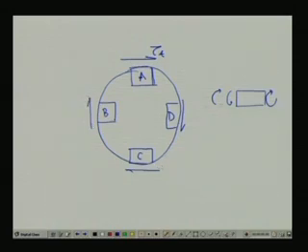And if we look at the vertical shear stresses, what is happening? This is the shear stress due to the vertical load. What will be the shear stress due to the vertical load at this point? It will be 0, because Q is 0 here. Similarly, the vertical shear stress over here will also be 0. This was tau t and this was also tau t.